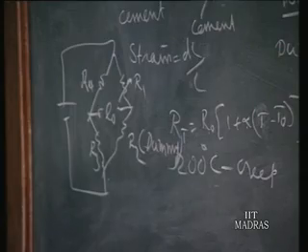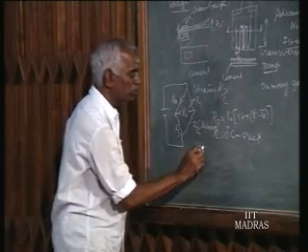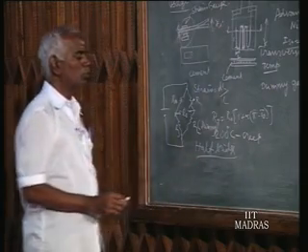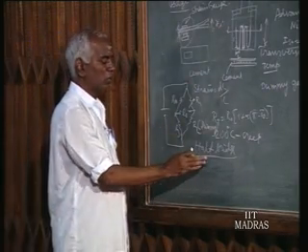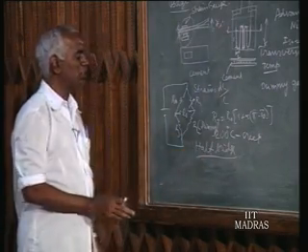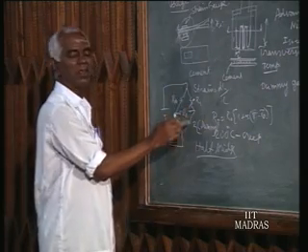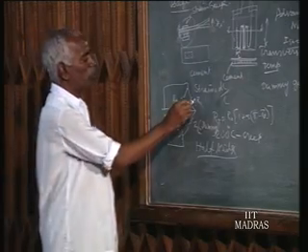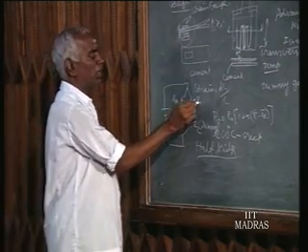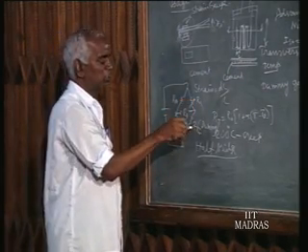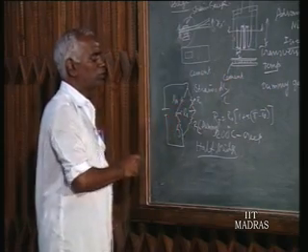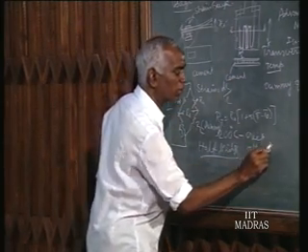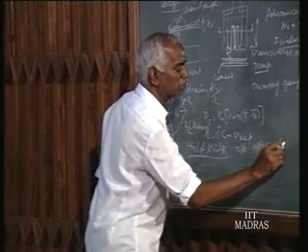For half bridge, we know that is half bridge. There are two situations you will be using half bridge. That is when the stress and strain are opposite in polarity, you are connecting in the adjacent arms. That is one is in tension or resistance increase, other one is resistance decrease. Then you will be using in adjacent arms, that is opposite effect, we are putting in adjacent arms.